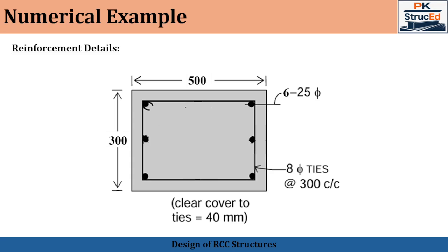So practically this uniaxial bending occurs in edge columns, normally in a building where the columns are provided on the edges, and in columns supporting eccentric loads as well as wind and seismic conditions. In real practice, we know pure axial loading is extremely rare. In the next lecture, we will extend this concept to columns under biaxial bending. Thank you.